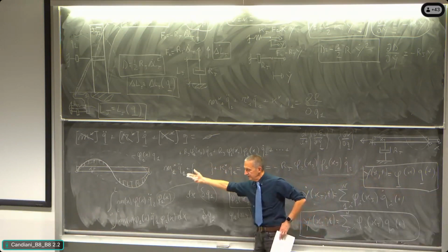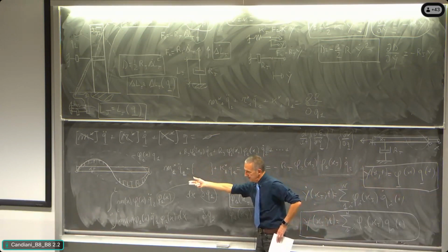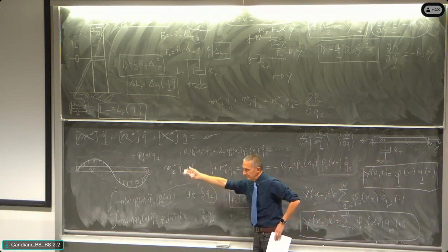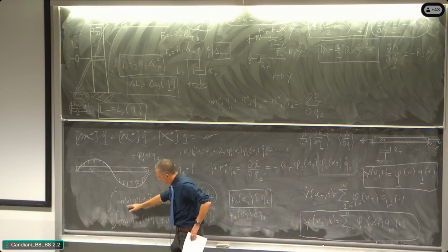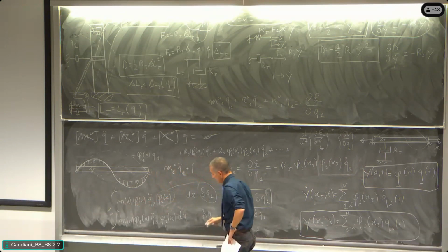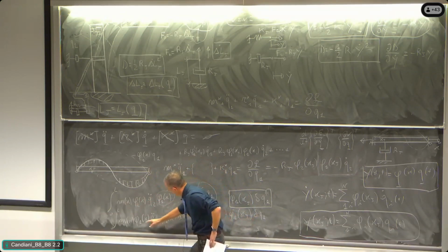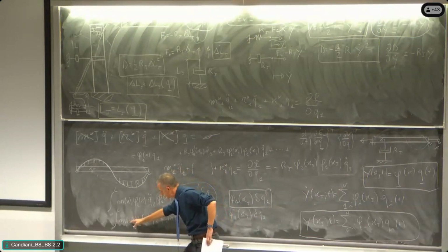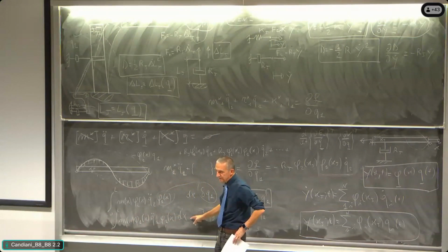And so I am giving a virtual displacement to the system along the first coordinate. And then I write the effect of that, the way in which all of that makes work associated to all the forces that are distributed. And so the distribution of mass, the distribution of inertial forces writes for the first mode an effect that is phi1 multiplied phi1, so phi1 squared, mass phi1 squared, integrated over dx, that is actually m star 1, all right?